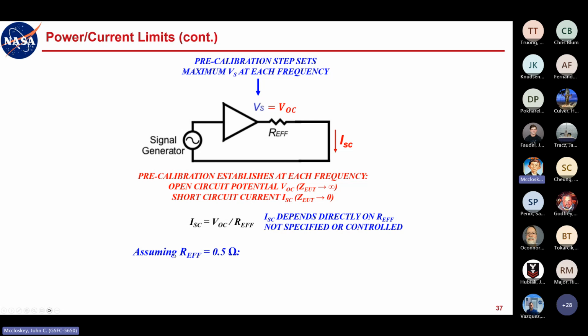If you are using one of these standard amplifiers, which we do here at Goddard, and I'll show you that one on Wednesday when we're in the lab, your physical output impedance is 2 ohms, mapping to half an ohm at the transformer secondary.